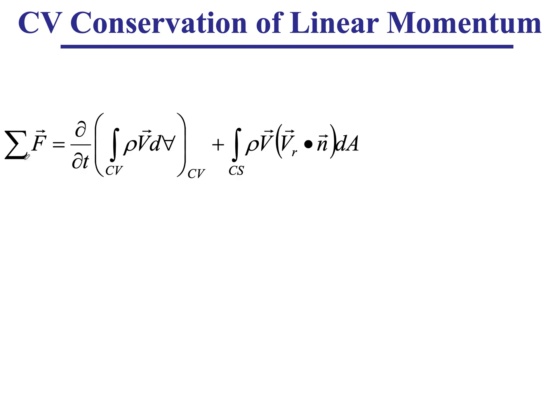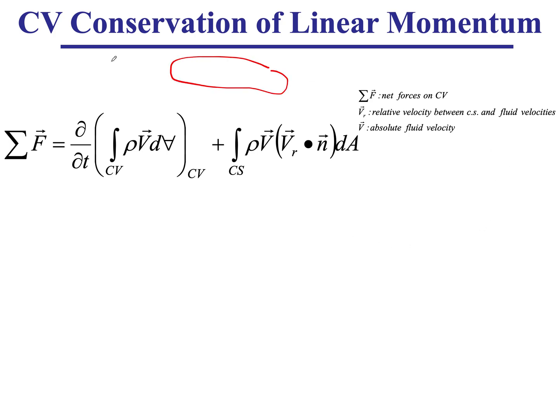So this is our starting point right over here, and let's look at the terms that are involved in this formulation. So we have a controlled volume, and in that controlled volume, masses could be coming in, and as these masses come in, they carry fluxes of momentum with them. They carry momentum just because the velocity of a mass is associated with momentum. In its most simplistic form, the summation of forces for a fixed mass would be equal to mass times acceleration. This is what we are familiar with.